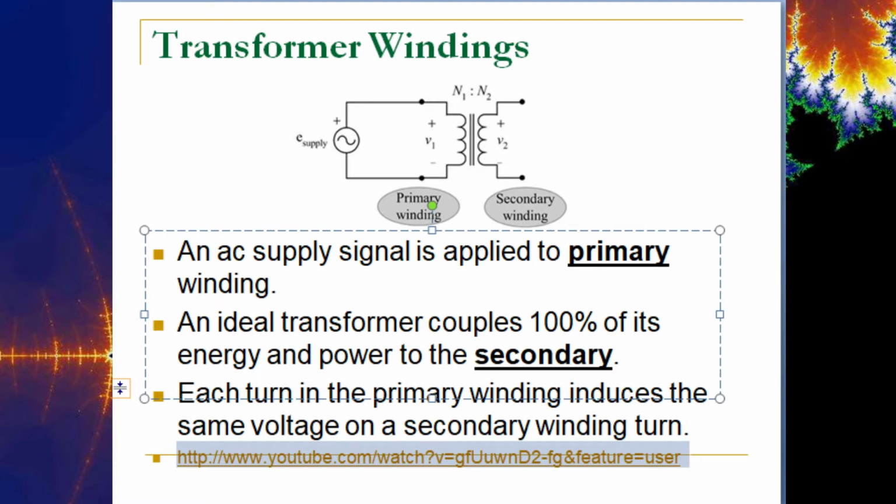Okay, so here's a short video from MIT that kind of shows this mutual inductance, and not even in a transformer setting. They actually created an inductor radio where they had the output of the radio into a coil instead of a speaker, and then on the secondary side, so to speak, they have another coil of wire which is connected to a speaker. So the radio to the coil of wire on the primary, and then a coil of wire connected to a speaker on the secondary. There's no physical connection here, but they're going to be playing some music through this mutual inductance.